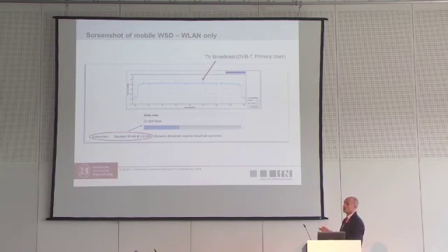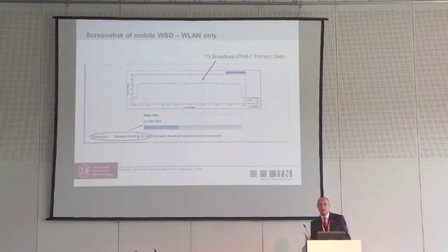This is the state 1 of the demonstration, where temporarily the DVB-T network is operated at the primary side. So we have only wireless LAN connection at 2.4 gigahertz, resulting in maybe something like 20 megabits per second in this case. It's rather difficult here at IFA to establish such a good connection, so if you come to our hall, you will see something like 10.